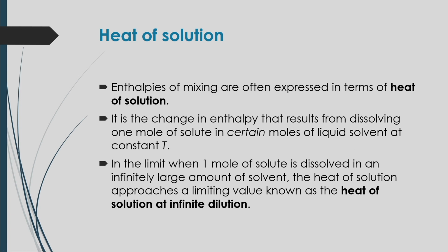Similarly, you can express how heat changes for a solution based on that enthalpy calculation, which is called the heat of solution or enthalpy of solution. Enthalpies of mixing are often expressed in terms of the heat of solution. It is the change in enthalpy that results from dissolving 1 mole of solute in a certain number of moles of liquid solvent at constant temperature. When 1 mole of solute is dissolved in an infinitely large amount of solvent, the heat of solution approaches a limiting value, which is known as the heat of solution at infinite dilution.